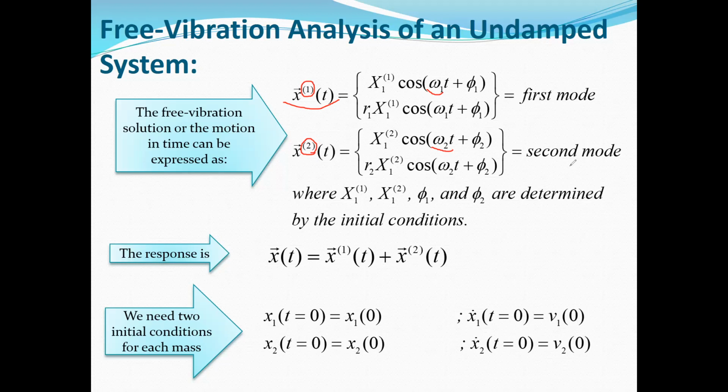When we deal with a 2 degree of freedom system and we extract 2 mode shapes, it means we can later understand the position of the masses with respect to each other during the vibrating motion by using these mode shapes. And later in the examples, you will see exactly what the application of these mode shapes is.